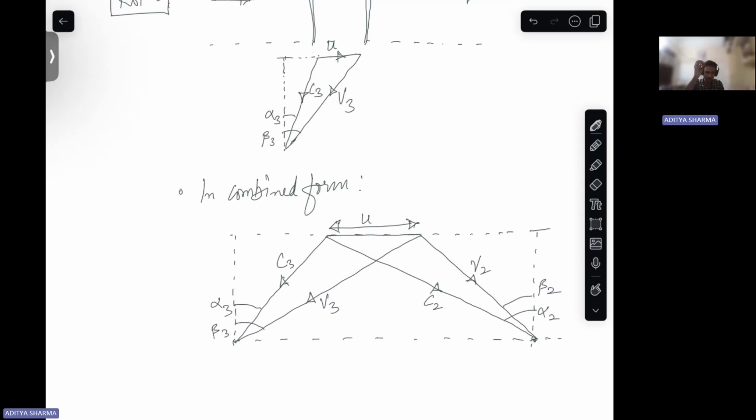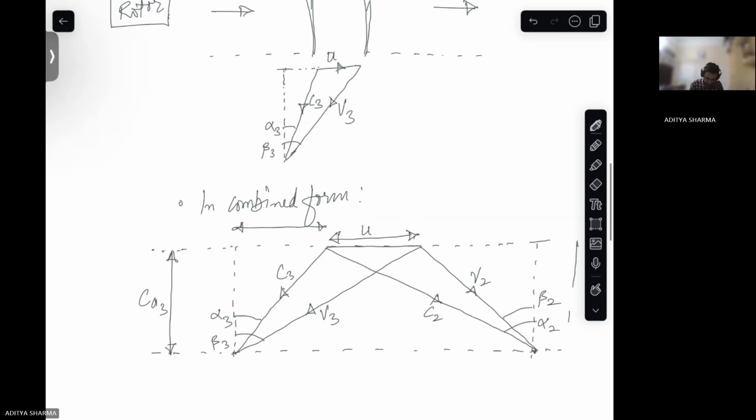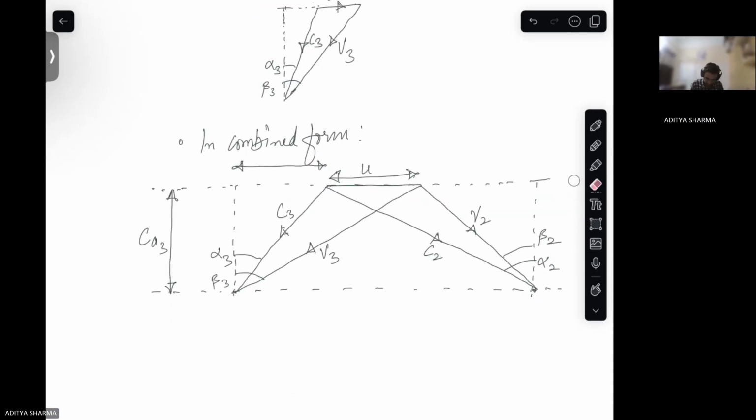Then tangential velocities also we can write. So for C3 we can split this. There are two directions involved here. Radially, we assume that there is equilibrium from your free vortex design. This is CA3. Here, this is CA2. Okay.